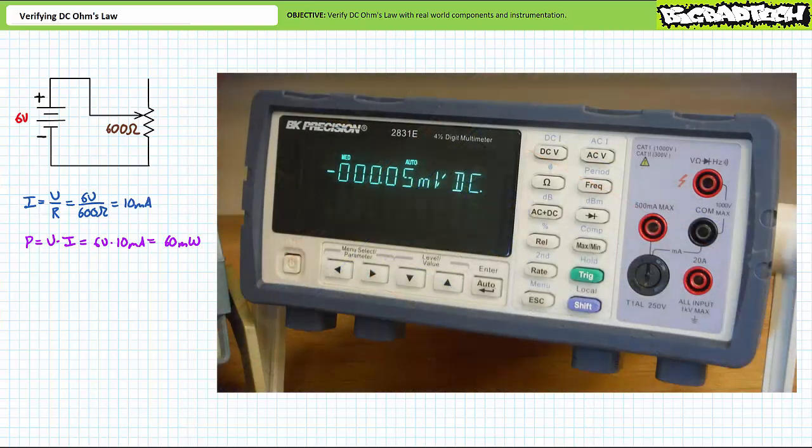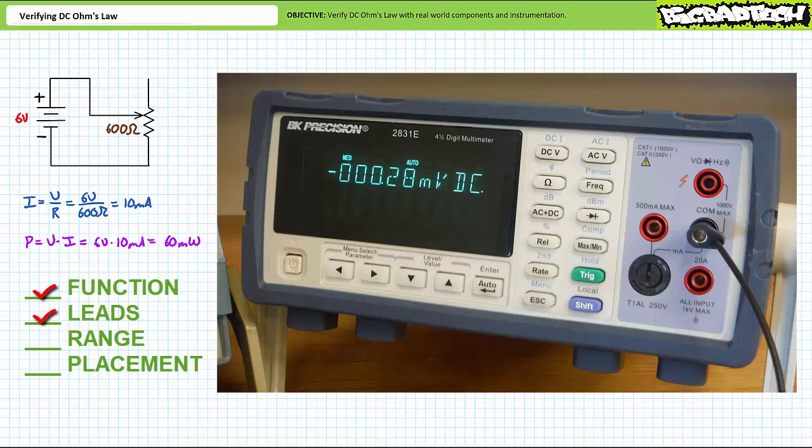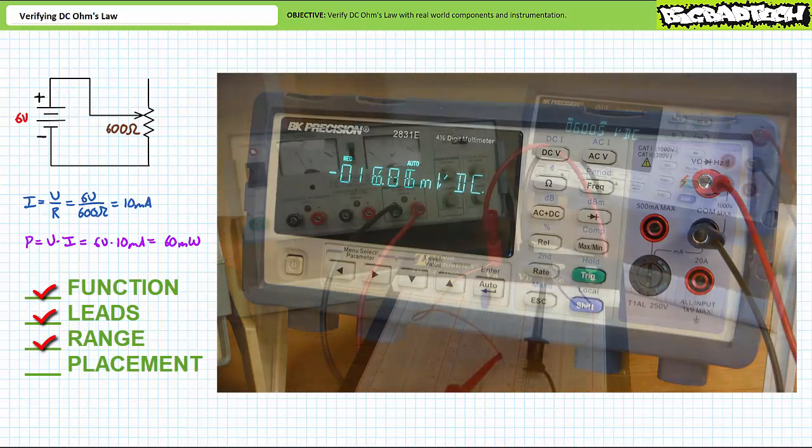Let's now use a DC voltmeter to establish a 6-volt source using an adjustable DC power supply. To place the DMM in DC voltmeter mode, use the checklist to do so. Function, leads, range, placement. Function. Choose the DC voltmeter function. Leads. Black lead into the black common hole. Red lead into the hole marked with a volt symbol above it. Range. Don't worry about it. This particular DMM is auto-ranging.